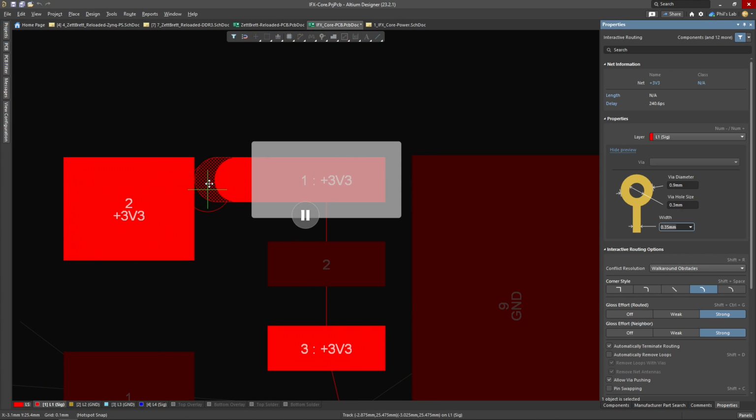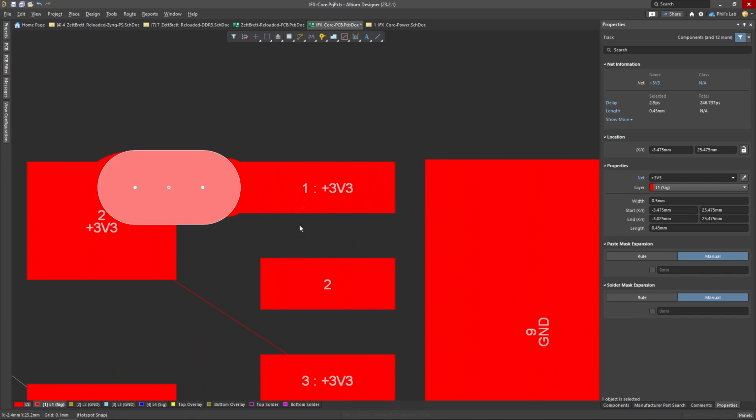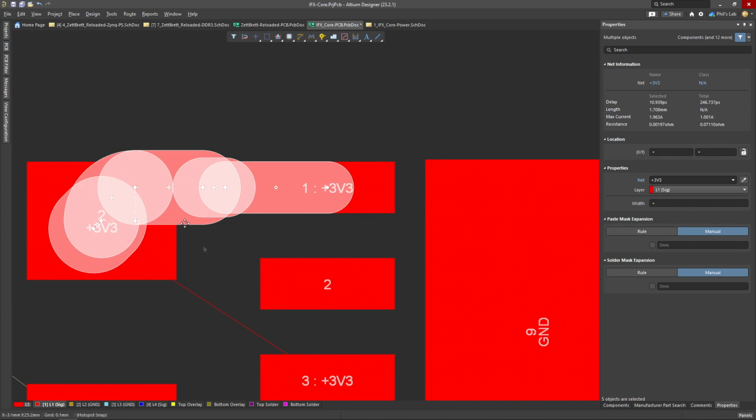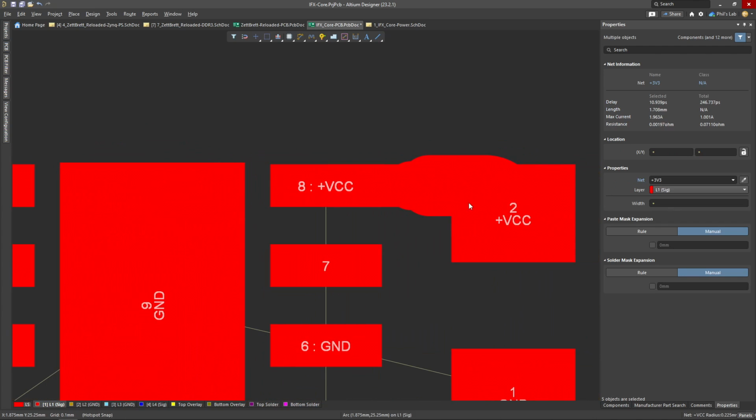We can root out and then, for example, increase our pad width incrementally like so. We want wide, short pads to reduce the inductance of our connections. We can then take this trace, copy it, paste it, and flip it, and then we have the same connection, for example, to our VCC, our power input.